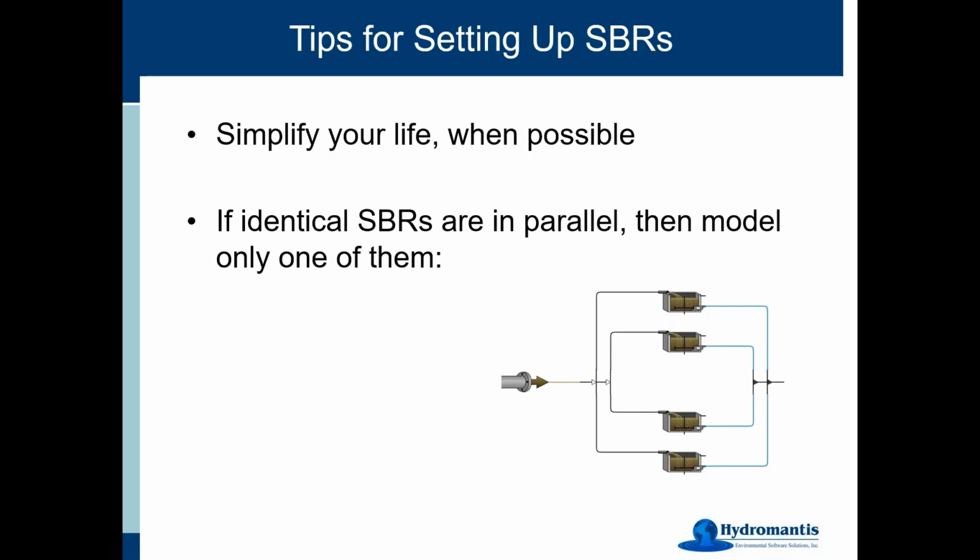So if you have identical SBRs, and by identical I mean they're receiving the same loading and they're also physically identical to each other in terms of their volume and so on, then you don't really need to model all of them in parallel, because if they're identical and they're receiving identical flow, they're going to predict the exact same results for all 4 SBRs. So rather than worrying about trying to sequence all of that stuff, just do one of them, and then you'll know that's going to be exactly the same concentration that would have been in the other ones.